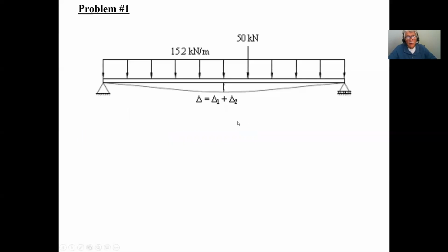it's being positioned. And then of course, the total deflection is the deflection caused by the distributed load plus the concentrated load. So I add them both together, because I can do the algebraic sum since I've calculated them both at the same position along the span. And I end up with 33.3 millimeters. And I think most of you got this bang on. So thank you very much for doing so well.